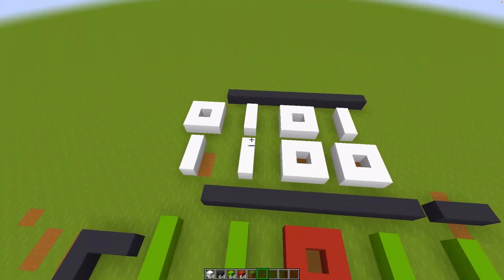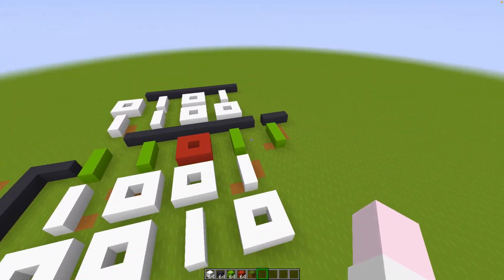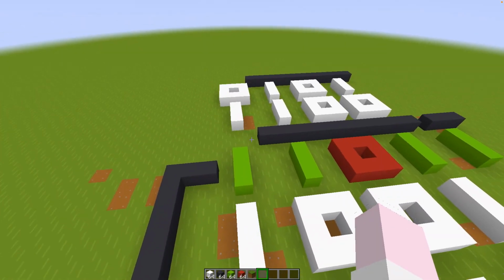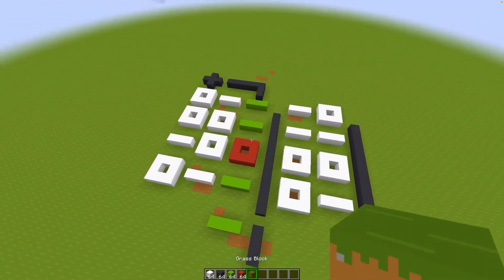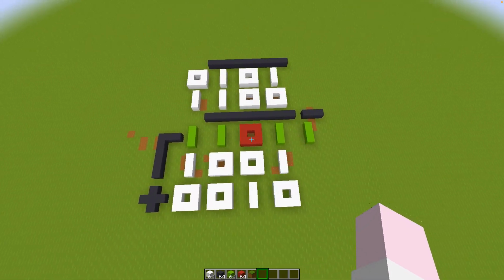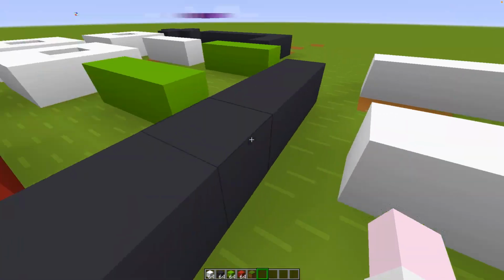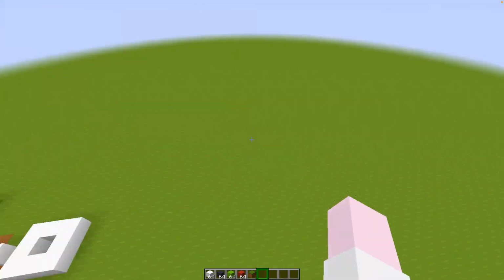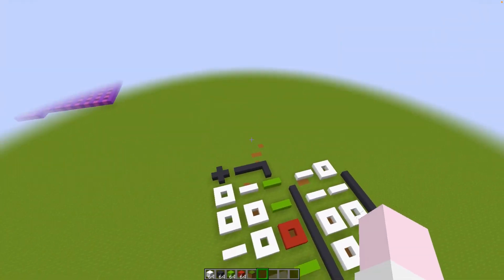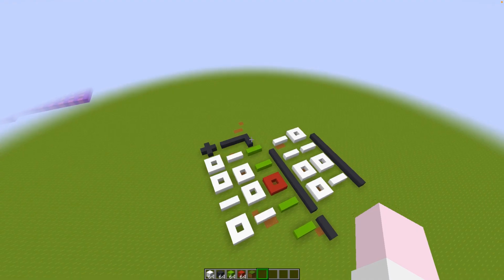For example, if we do 3 minus 5, then we will get the 2's complement of 2, and this bit will be a 0. So that's pretty nice, because then we can just put it straight back into any addition without even having to turn on subtraction, because we already have the 2's complement, so we don't have to get the 2's complement again. Anyway, let's make a carry cancel adder.